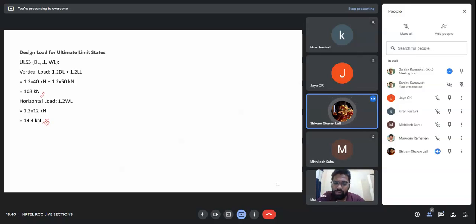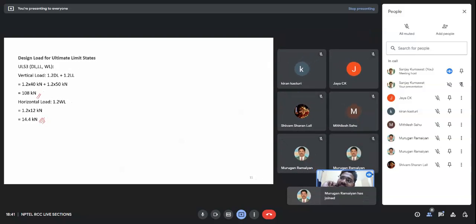Sir, I want to ask, in a multi-storied building, when will we use the wind load condition? There must be some limit, earthquake or wind. For five floors we may not require an earthquake analysis or something like that. Yes, definitely. There is an IS code. We have IS 875 Part 3, which is specifically for wind load. So you can check that code and see the various criteria, or the various heights of the building, for which wind load is to be considered.